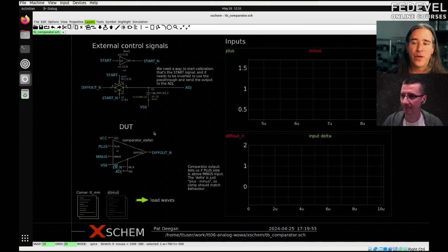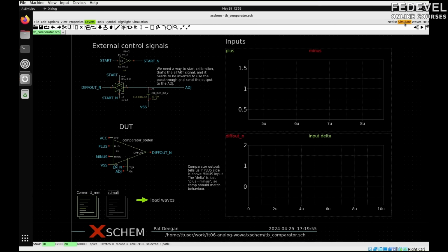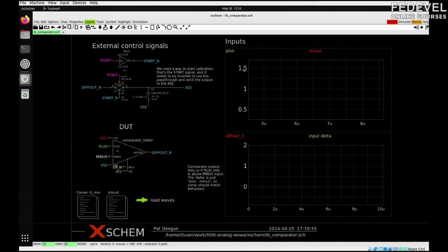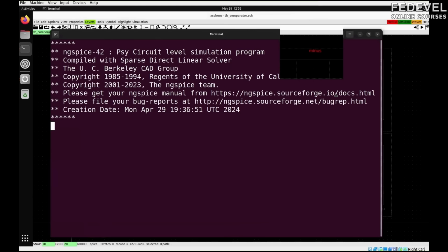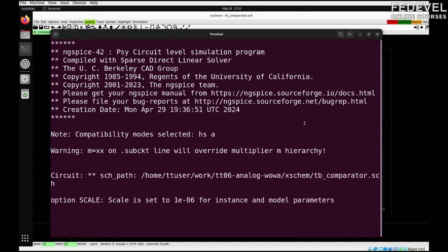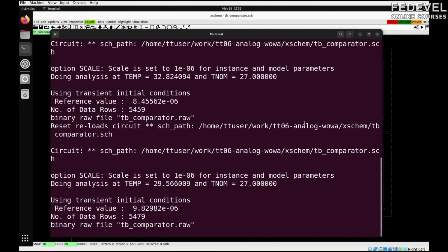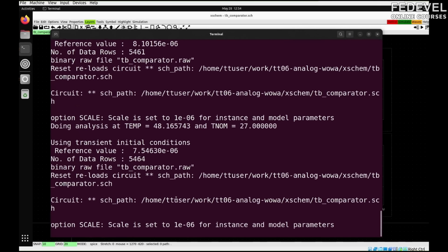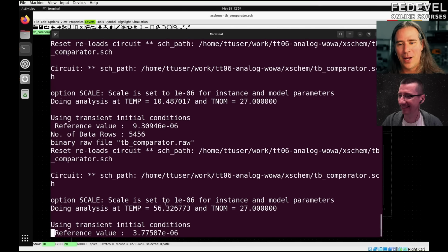So once you have your Spice and all your stuff, you just basically go, oh, sorry, play. You need to play. Yeah? No? Is there a play button? Yeah. So you say netlist, and then it's complaining because it doesn't know that I used the stimuli file. Simulate, it launches ngSpice, and then now it's doing all these different runs. And you can see the temperature vary here, 19, 65, 53, 15, minus 54, ouch. So it's going, and I think I did 20 runs.